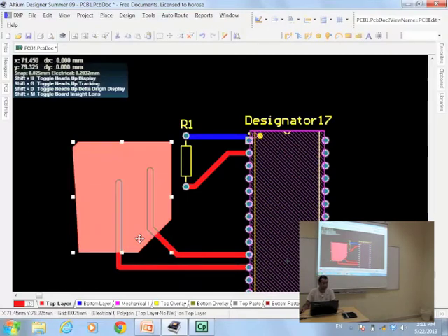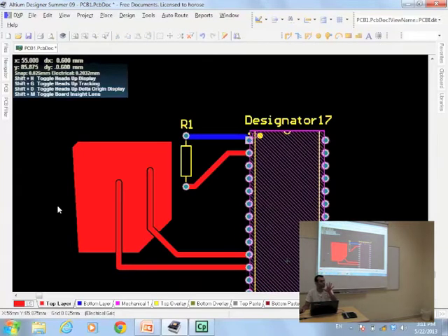And you see, when I cover it, my tracks don't go into the ground plane. It's out of it. But don't do that, because in this university we use milling and we don't cover it. If you look at my PCBs, all of the places I don't want to expose to soldering are covered by something green, so I can solder them. But if you do what I did and use it here without that cover, your solder flows over them, and it's a big headache to remove. So this is not okay.